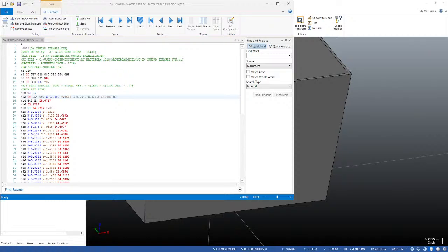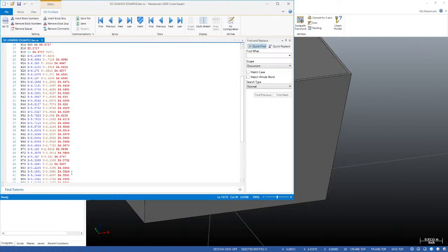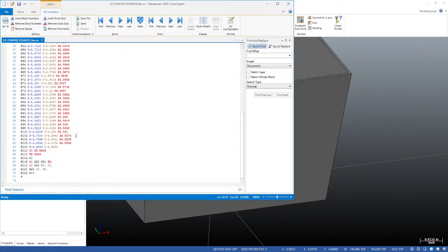Okay, so this is all well and good, but we've gotten a rotation position, and then we're just getting a bunch of X, Y, Z output. So all it's doing is outputting tooltip point after point, and doing 72 lines of code to cut this right here is a lot, right? It's pretty ridiculous. So I'm going to go into curve 5-axis here, and I'm going to say maximum step. Let's go 6 inches and see what that gets us.